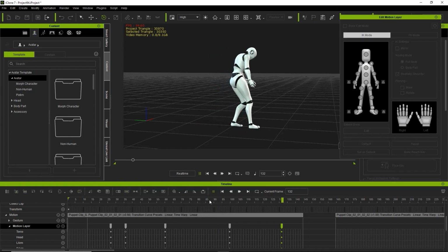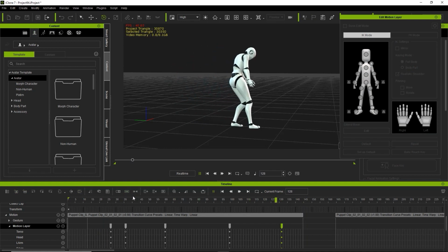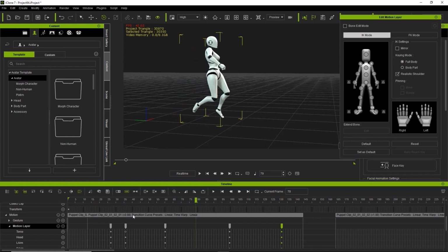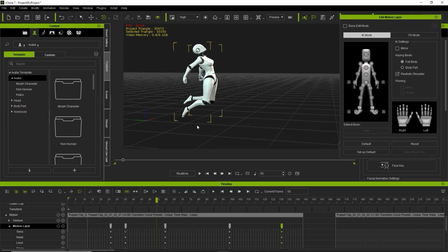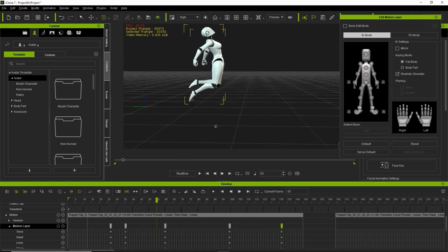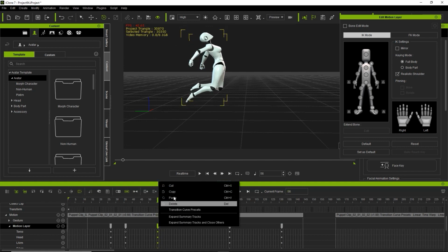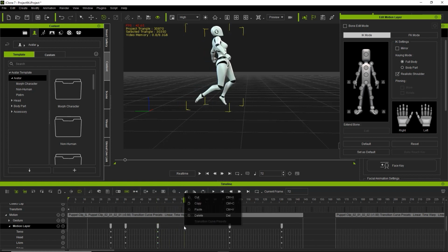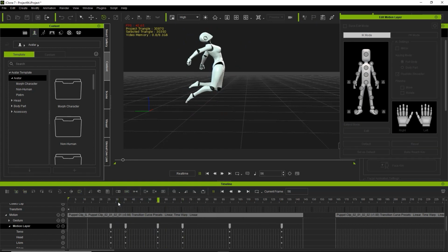Okay, so it looks like this. And now he's, there we go. So now if we play back, that looks a little bit better. And again, don't worry about the time. We're going to enhance that a little bit further. What we want to do is get this basic stuff down. So we'll have like this. Maybe if I want him to launch into that, we'll call it a thrust, a little bit earlier, a thrust forward, we can click and drag that main keyframe there, the absolute key. We can also right-click and copy that keyframe and maybe paste it a bit further down if we want to have that pose a little bit longer. So that's like this.